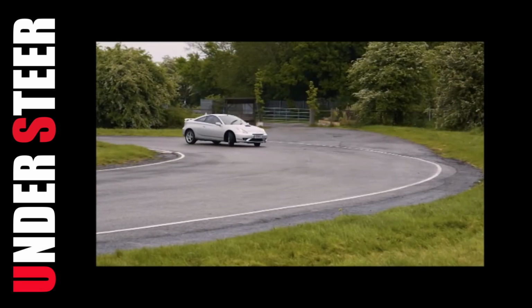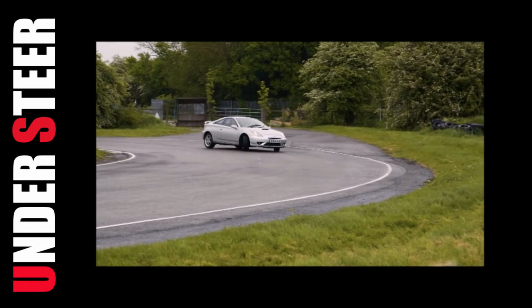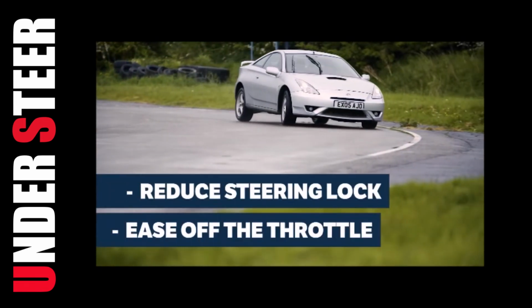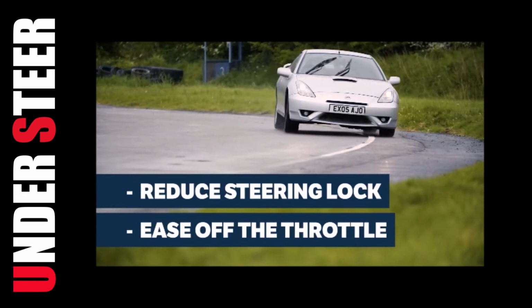It means that the vehicle is not steering enough, and to compensate for it, all you do is reduce your steering lock and ease off the throttle slowly. Do not apply the brakes.